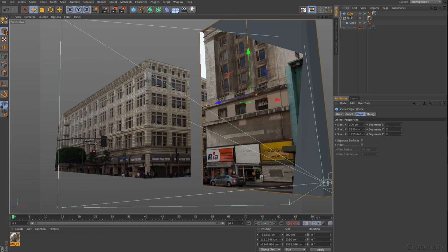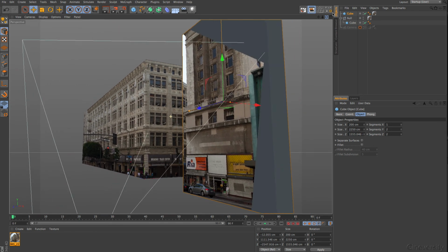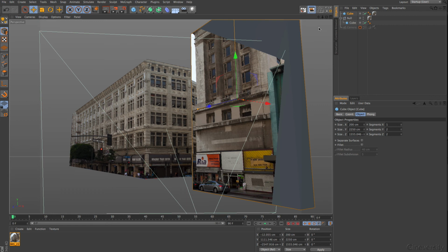But here we want to go, of course, first through the projection calibrator or camera calibrator. And this gives me already a nice little game here. So I can play with that and maybe already set up a little camera. Now comes the question, of course. We want to have from the other image exactly the same position that we have with this building now, but from the other picture. And the other picture needs to be set up in the same way, so that we have the same orientation for the axis, and we set in a vertical line exactly the origin point to 0, 0, 0, and then we can replace this.